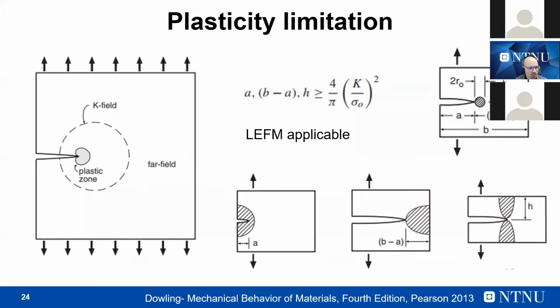So outside this small plastic zone, you can still approximate your stress field with the linear elastic assumption. And this is very important for all the methods. Usually as engineers, we want to have local approaches that are able to overcome the problem of plasticity. We don't want to use nonlinear equations to solve engineering problems, because this increases the complexity and the computational effort that you have to do. And so this is very, very painful and very difficult to do.